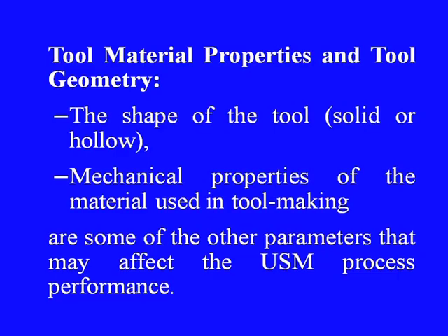Then let us see the tool material properties and the tool geometry. The shape of the tool, whether it is a solid tool or a hollow tool, in both the cases the performance will be different. The hollow tool will tend to get worn out very fast, whereas the solid tool will give better tool life as far as the wear is concerned.